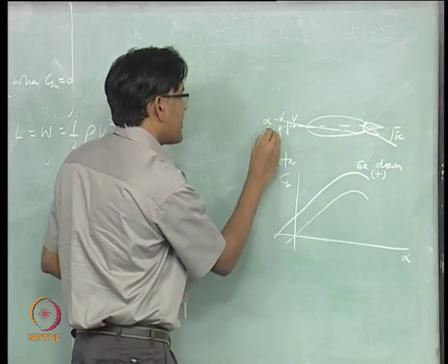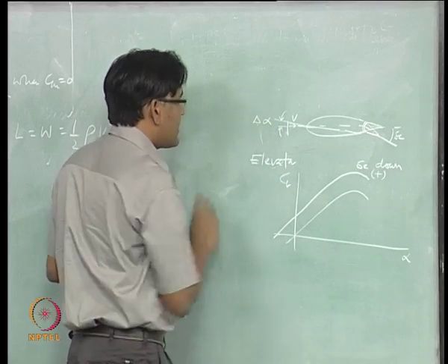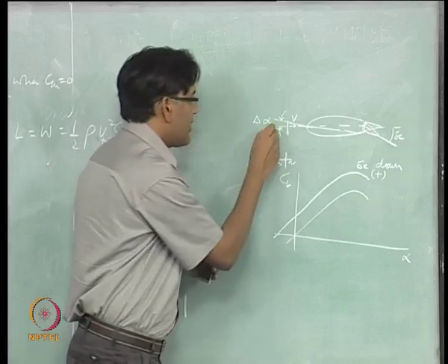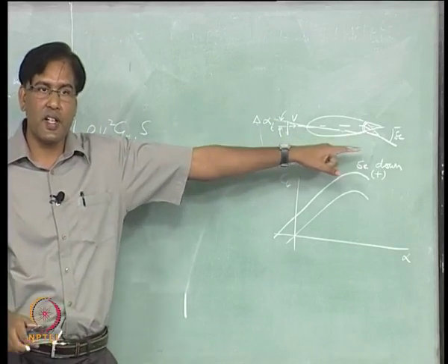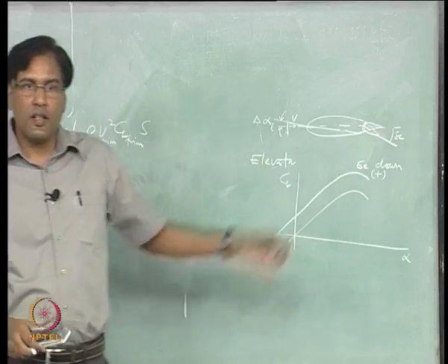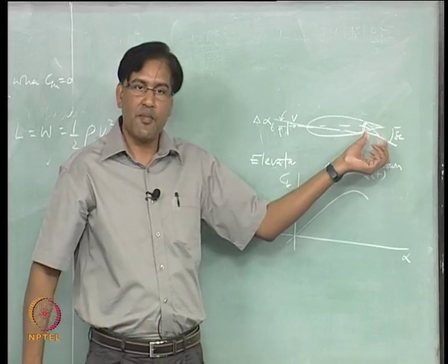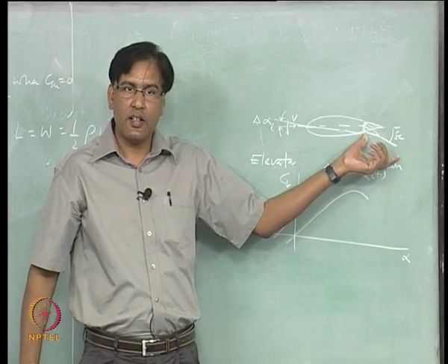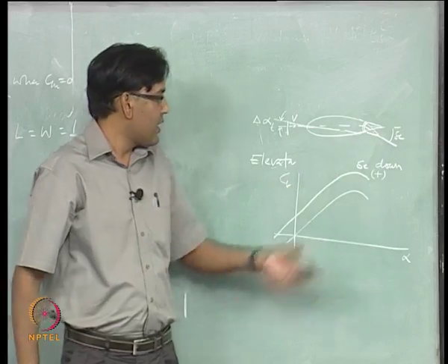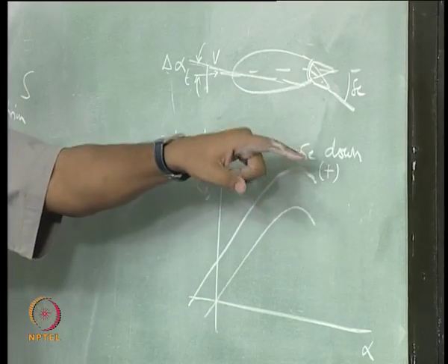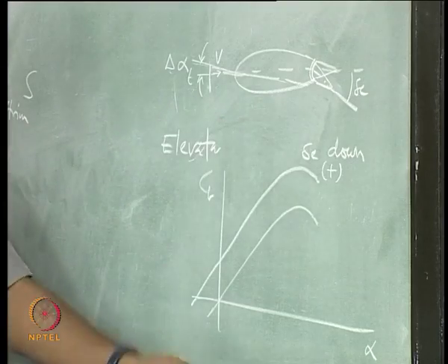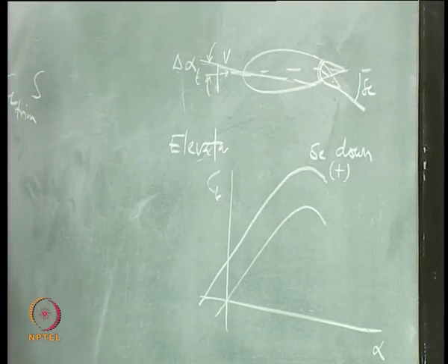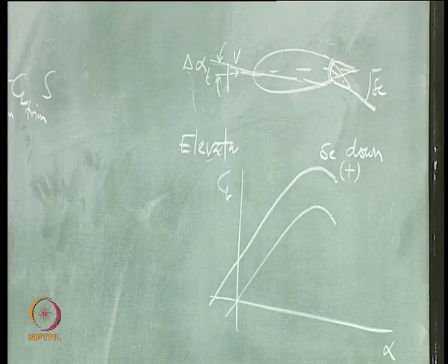I will say this alpha at the tail, change in delta alpha at the tail because of the deflection of this flap, right. And the positive convention is that you take it positive down, because it is going to give you an increase in lift, positive camber, right.